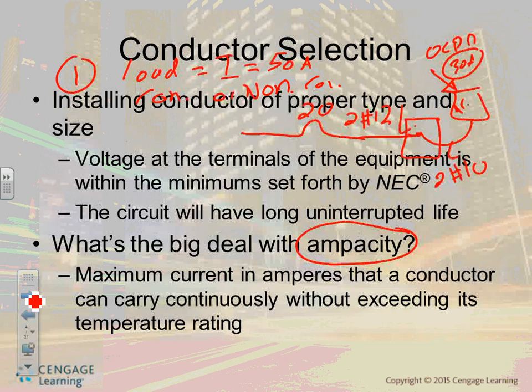Non-continuous. That's the first thing. What do you do with the continuous, gentlemen? 1.25. What do you do with the non-continuous? Leave it alone. That makes sense? First start with the load. Is it continuous? Up to 25%. Is it non-continuous? Leave it alone.